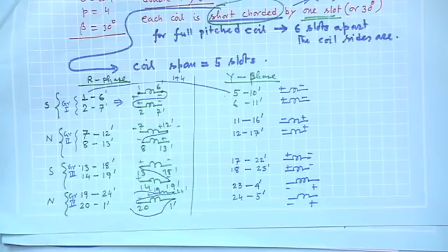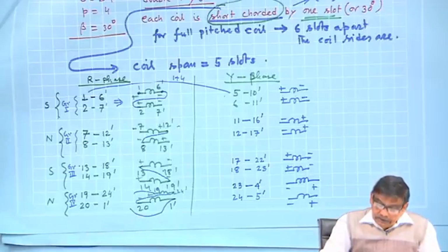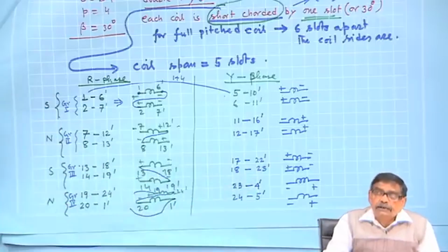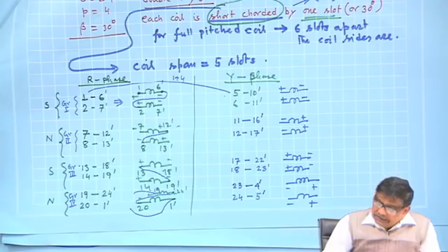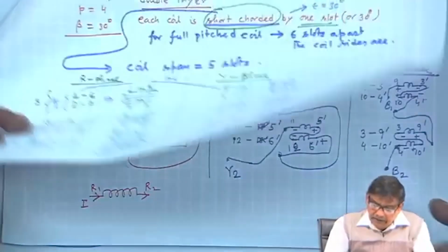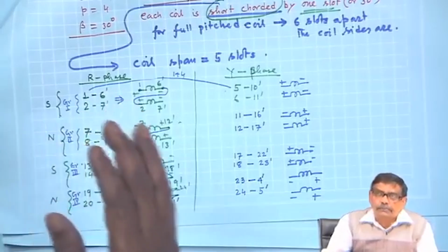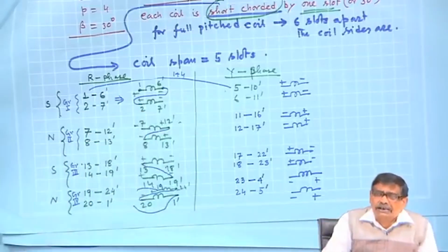So, generally for high voltage machines, the coils will be connected in series, so that it gives you appropriate voltage. Of course, no one stops you if you connect the coils in parallel and then specify the voltage. So, this I will not tell. See, winding is a very big thing. There are other types of winding, fractional pitch winding, this, that.